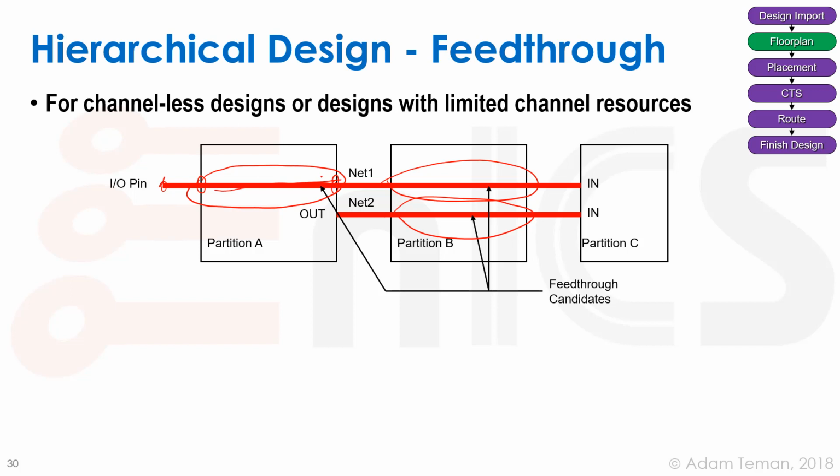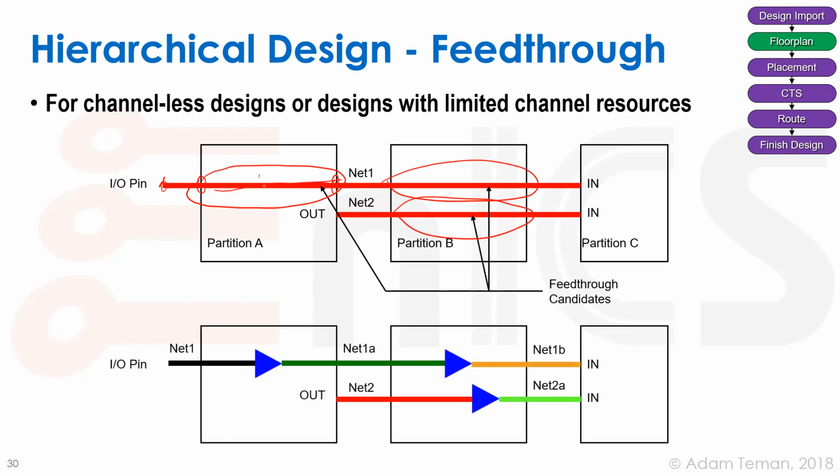But there is another problem. Let's say we want to do some sort of optimization, such as adding a buffer inside here. We can't do that. Then we have to push the net down into the net list, and that allows us the possibility of actually, say, buffering one of these nets inside a partition where the net doesn't actually exist. Okay, so that's another kind of a headache that we have to deal with when we're dealing with hierarchical design. So that was all I wanted to say about hierarchical design, and it leads me to the Chip Hall of Fame.